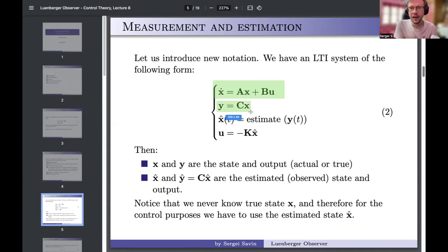We still have our measurements. If you remember, we discussed this part earlier. Let me point it out now. y equals Cx. What is this? Well, in lecture number 1 and maybe lecture number 3 or so, we talked about it in terms of a variable we care about, right? We said that y can be the same variable as we use in ODEs and so on. All this is true. But here for today, we have a very concrete interpretation of what y is. Y here is a measurement. That is what you measure, right? So here, y equals Cx is what you measure. So your sensors basically transform your vector of states x into a vector of some variables y.